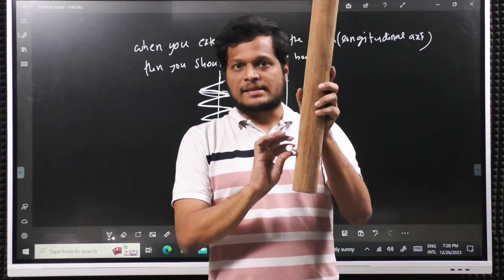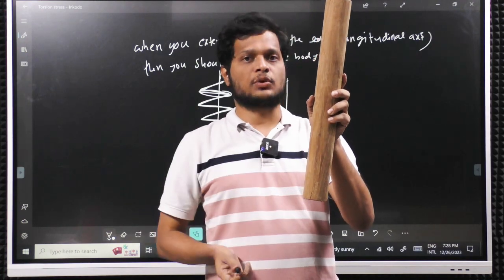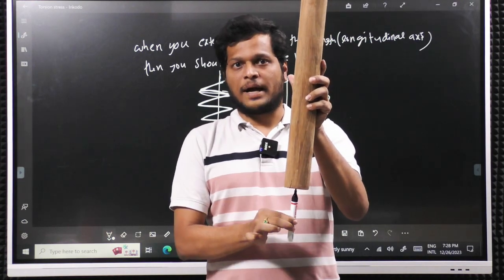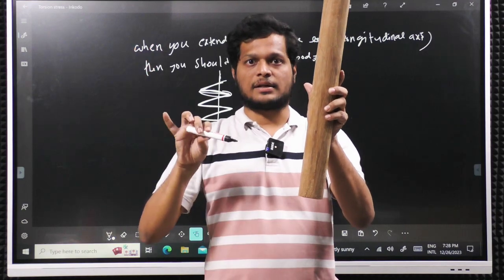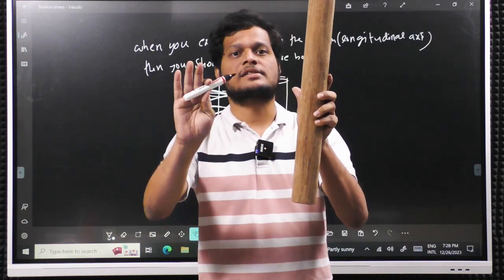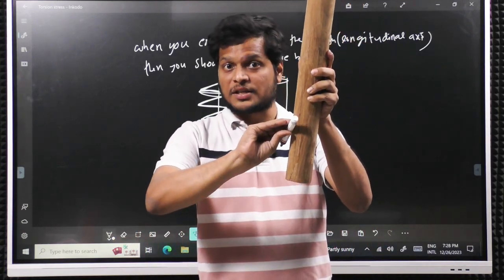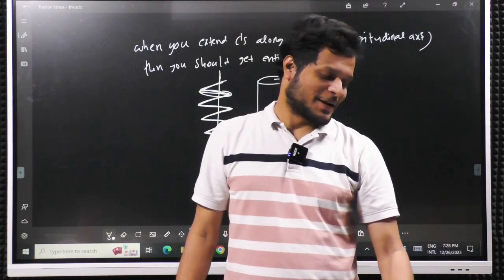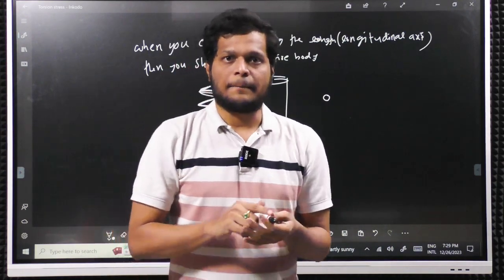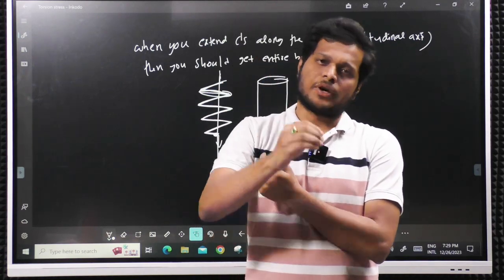If you imagine this as a straight line, instead of inclination, then see the other two axes. This will become y because you imagined as straight, parallel to the load line. I can remove y. Next, another is x axis. As this is a straight line, the perpendicular axis will meet the load line. So it is subjected to pure torsion. If I assume any inclination, then the axis will not become parallel, so it is subjected to bending. So a closely coiled spring, even though it has 10 degrees inclination, we assume it as a straight line.